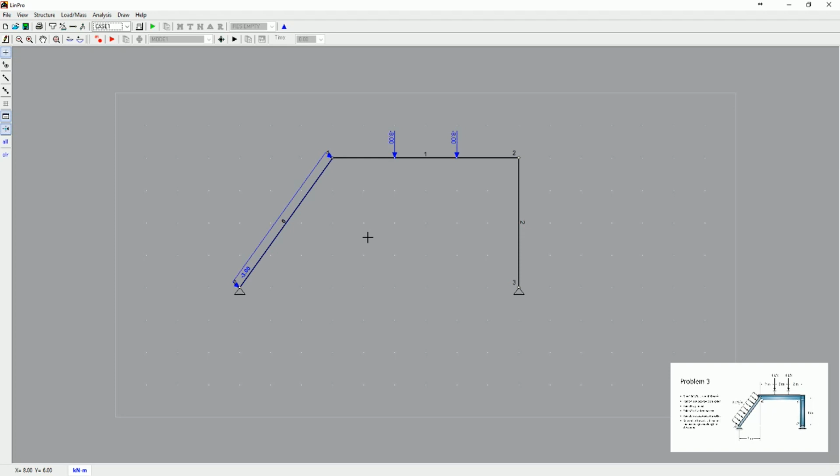All that remains is to run the analysis. Click the green icon. You can see the deflections. You can see that the section has moved to the right. These are the reactions. These are the moments. We can now clearly see the moment pattern on member 1. You can see that it's 3 segmented lines, whereas on member 0 we have a curved line.